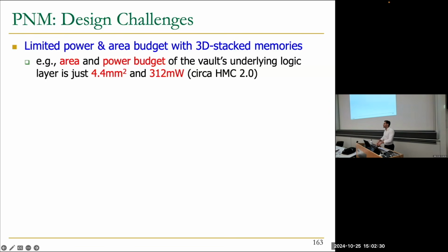But at the moment that you are decreasing your density, you're also potentially increasing the memory bottleneck that your application might suffer, because if you don't have enough space to store your data, at some point you're going to have to move that data in and then do the computation. So at some point you're going to end up in a processor-centric setup as well. We are going to see how this realizes in real-world applications, real-world chips that I'm going to mention later.